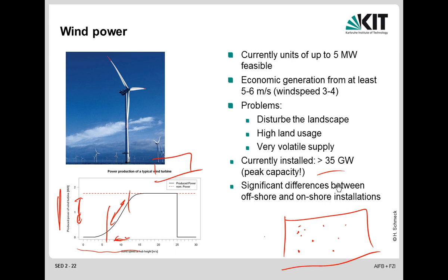And there is a significant advantage for the energy industry because the power system, the power grid, does not have to change if you have a central wind farm somewhere. It's just replacing the central conventional power plant in principle, but the whole structure of the power grid is not affected. Whereas an onshore wind power plant is connected to a medium voltage layer of the network, and so this is a significant change of the system.